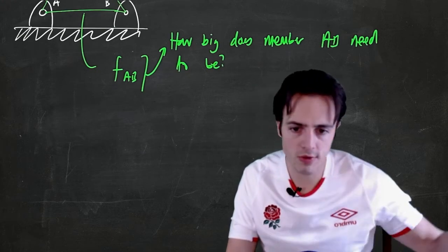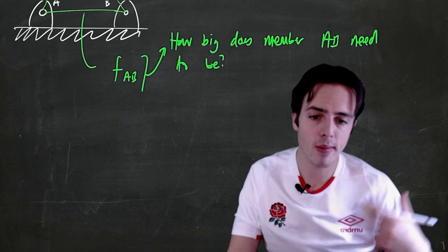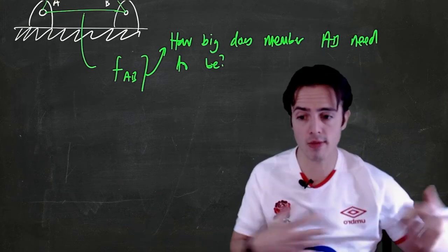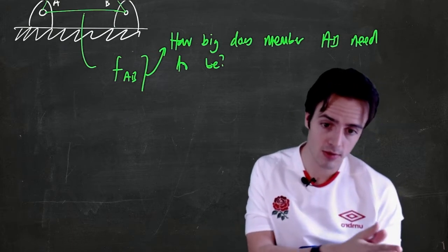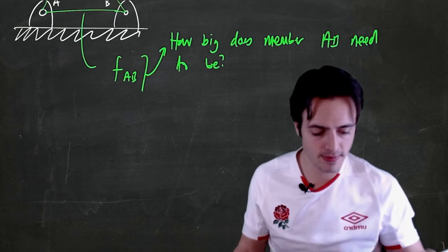Okay, so once we solve for all of those internal forces, which hopefully again is just revision, we can remember our constitutive relationships, which is Hooke's law. So we can remember that axial stress is equal to modulus of elasticity multiplied by axial strain.